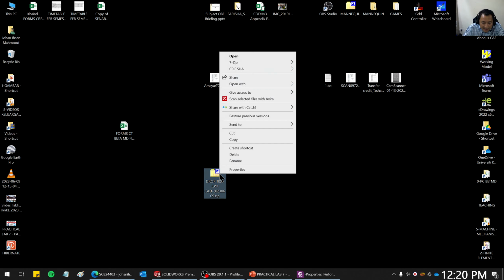So this motherboard, I need to create a new material. The material will be PCB. Right click, apply, edit material. I can go to custom material. There's one already created here. I can create a new one, new category. Board, maybe. Under that particular new category, I can right click and then create a new material, PCB.